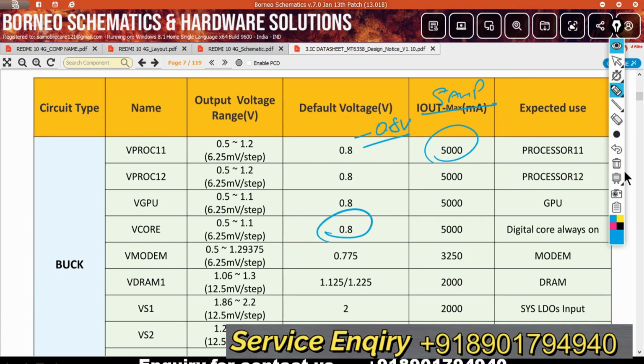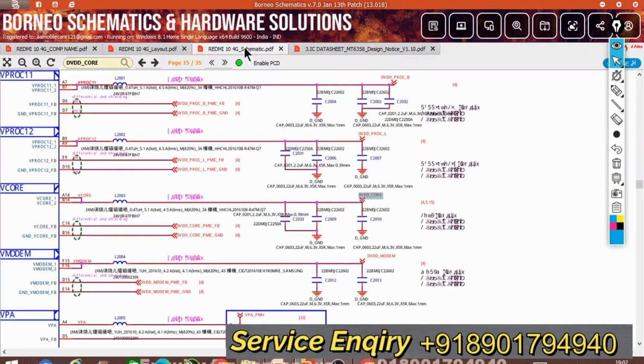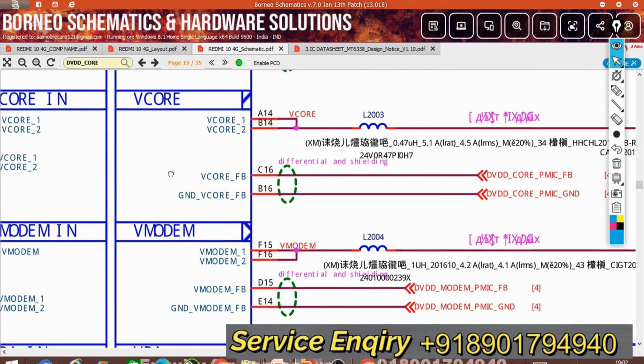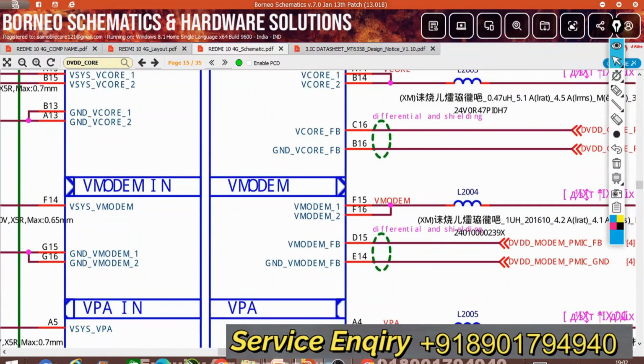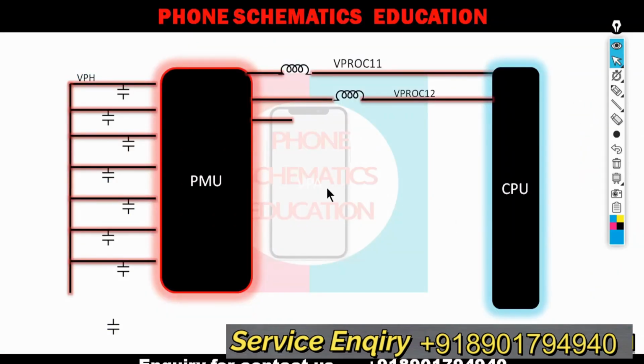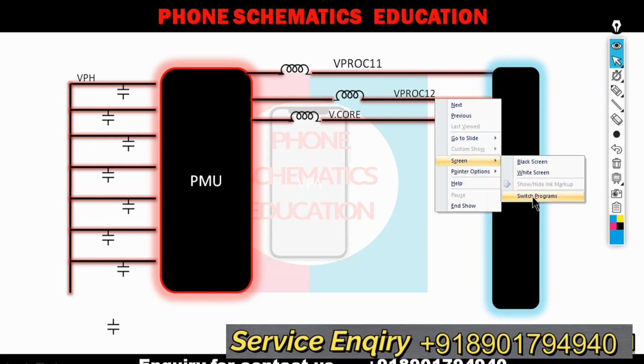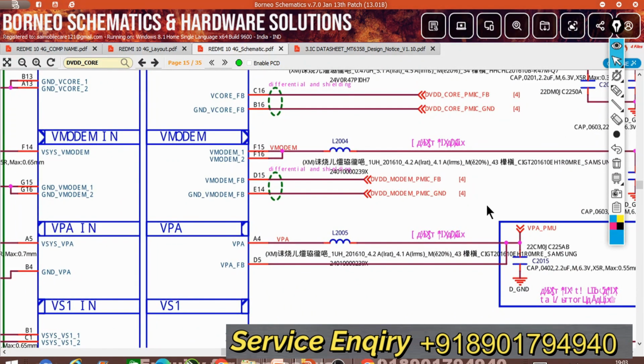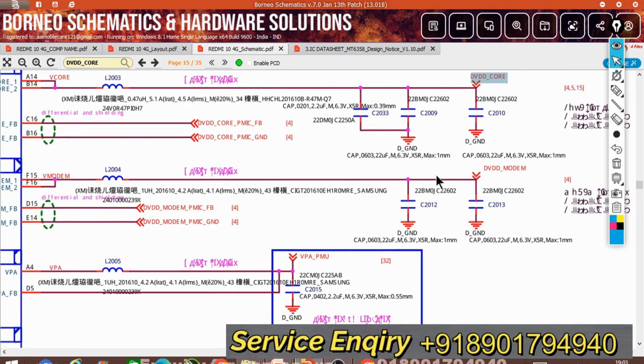So we clear this and go to the schematics again. I hope you understood. V core, the voltage for the core section, similar input for the core section. Let's withdraw this. After that, there is the core section called V core. In this line, similar, you will get 0.8 voltage. Now, after V core, there is another voltage called V modem, voltage for modem. This voltage also goes to the CPU.